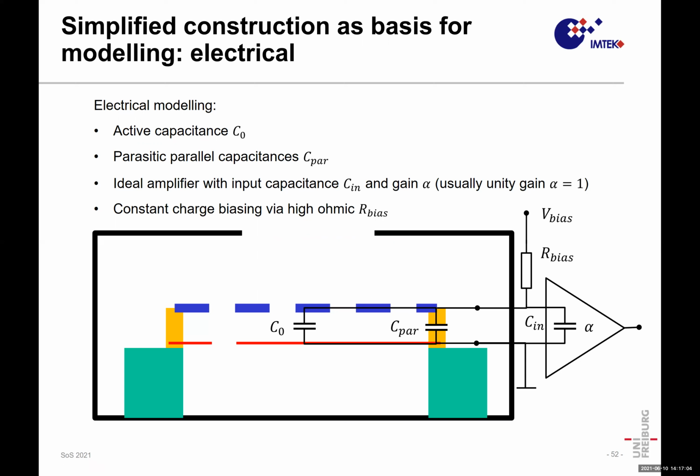So it is a critical parameter because whatever signal I generate here will be divided down by these parasitics. And of course, any amplifier that I have behind also has an input capacitance, even bond wires and stuff like this. The packaging will have parasitic capacitance. All of it is loading my active capacitance, and I have to respect that.